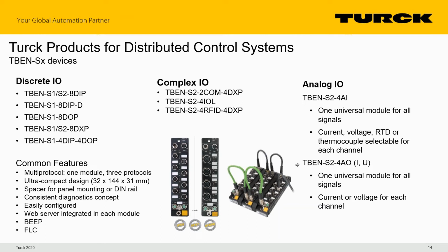Our analog output is similar. It is current or voltage, and it is software selectable by each discrete port. Our digital inputs are available as M8 or the M12s. The specialty modules and the analog I/O modules are all available only as the M12 connections.